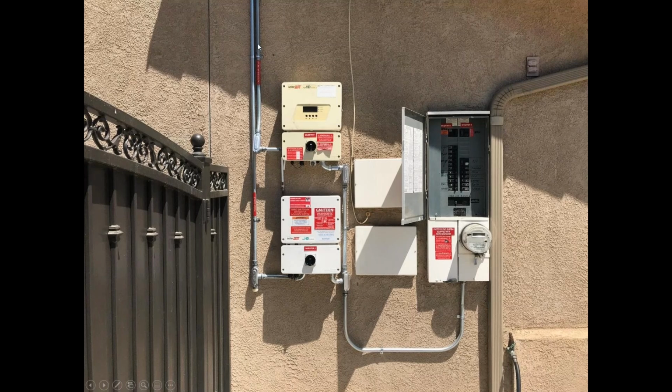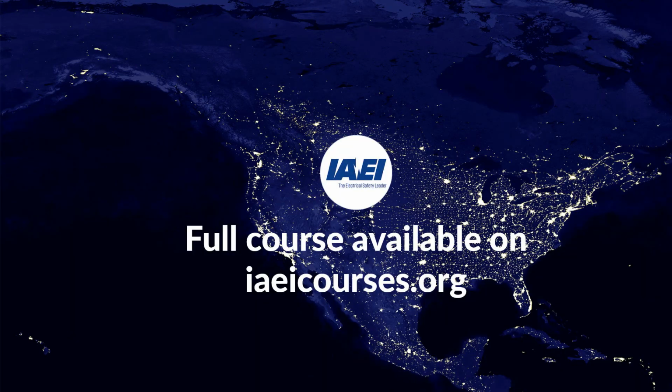So the conduits you see on the left coming down from the roof, those are the source conductors from the roof, direct current going into each of the inverters. They convert that direct current to alternating current, and it's connected to the existing service. These are utility interactive inverters. That means if the utility shuts down, these inverters will cease output. They won't produce electricity so that we don't backfeed the utility unintentionally.